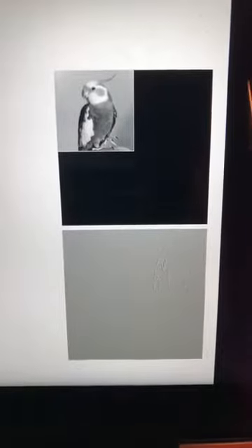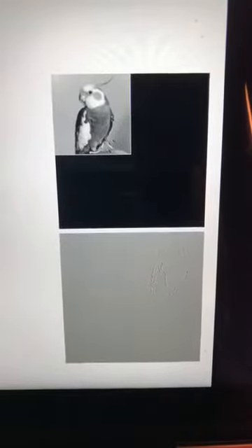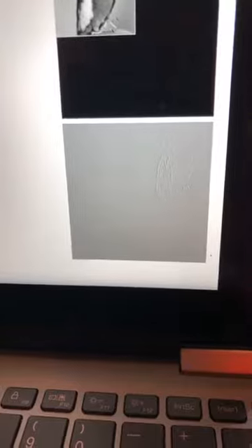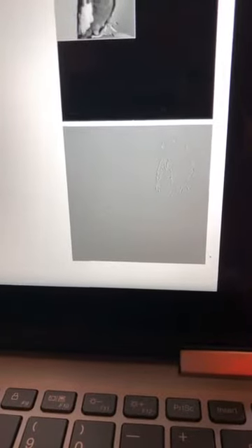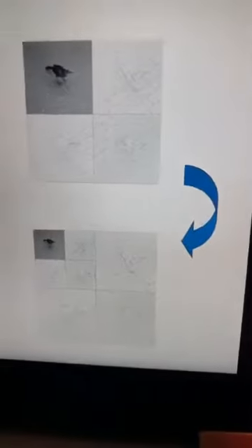So first you pass every column through a low pass filter and throw every other sample, then you pass every row and you throw every other sample. So the image is reduced into half, 1/4, half in rows and half in columns. So this is a decimated image. And similarly, you see three other images here. These images are that you are passing through a high pass filter and a low pass filter. So I'll be drawing this, but important is this image again.